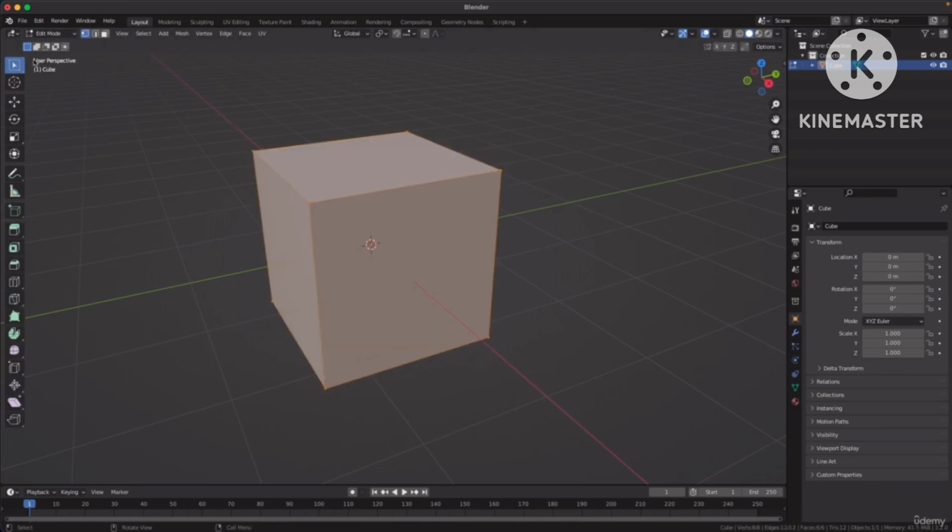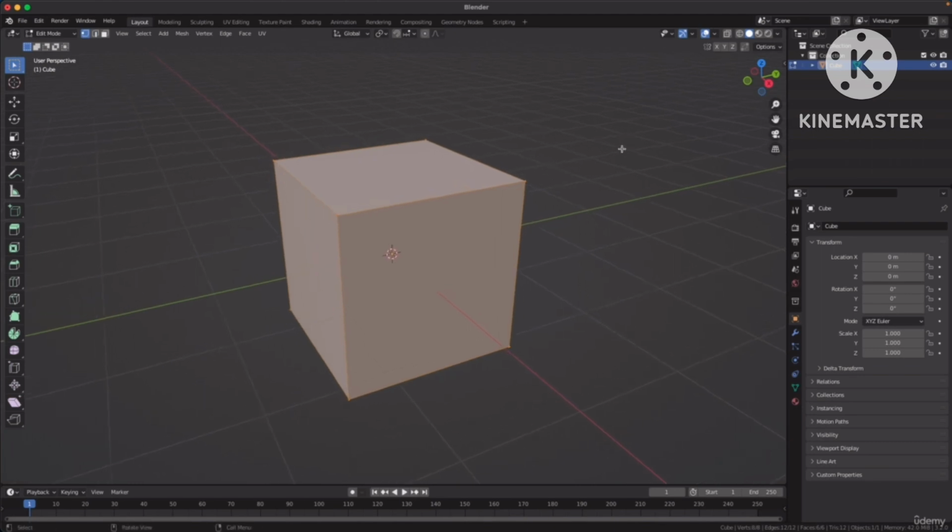You will see this drop down here at the top of the 3D viewport will change to edit mode. This is usually object mode. So if I press tab again, we are going to go out of edit mode and back to object mode. You can also use this little drop down menu here to change between object mode and edit mode, but it's easier if you use the tab shortcut. So click the object, press tab to enter edit mode, and you are now in edit mode.